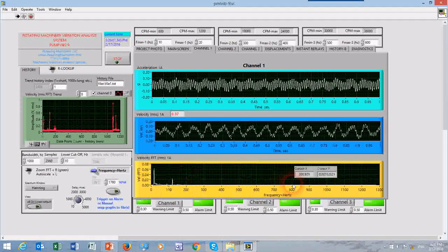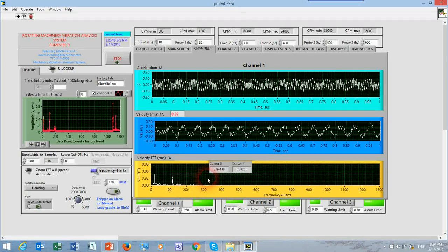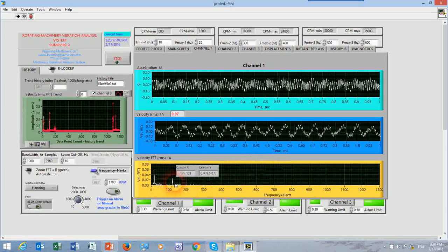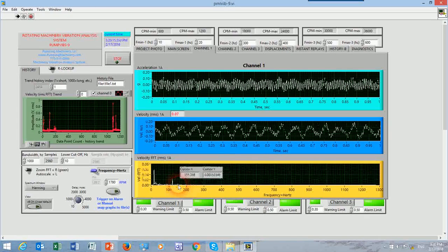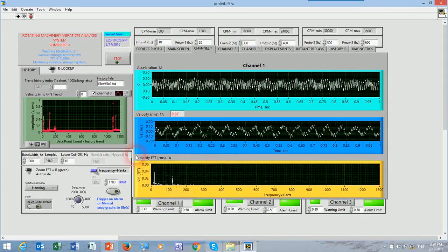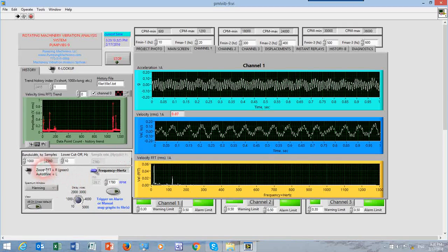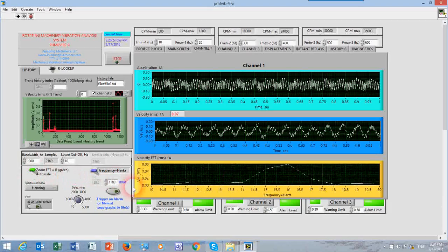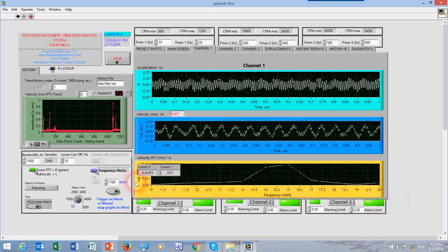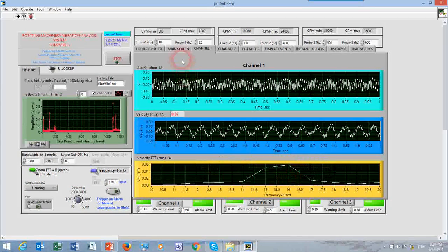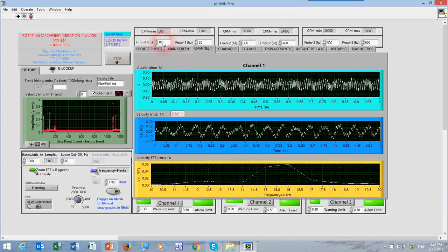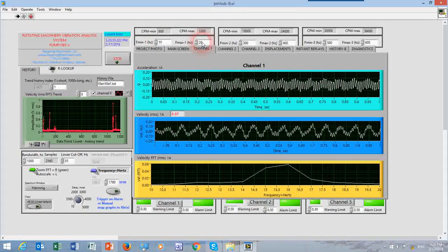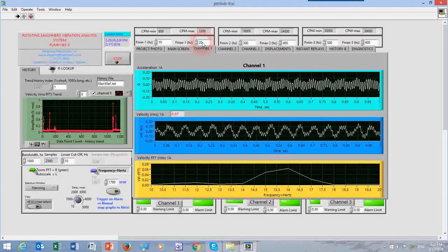Now let's see if we want to understand what's going on here in the area, sounds like between 0 and 150 hertz. So what we do now, we'll click zoom. The zoom button gets us a zoom to 10 to 20. Why from 10 to 20 frequency? Because on top of the screen we'll see a zoom minimum and maximum set for each channel, which can actually be set separately.